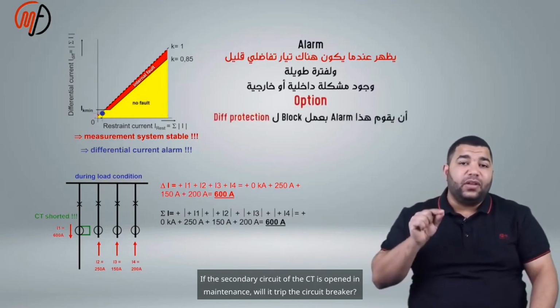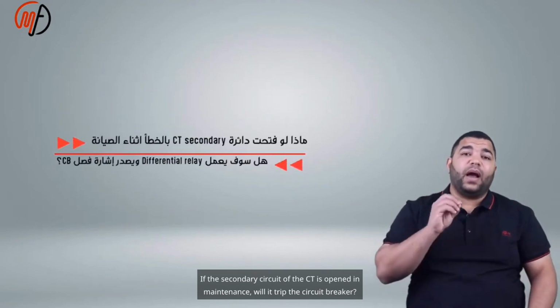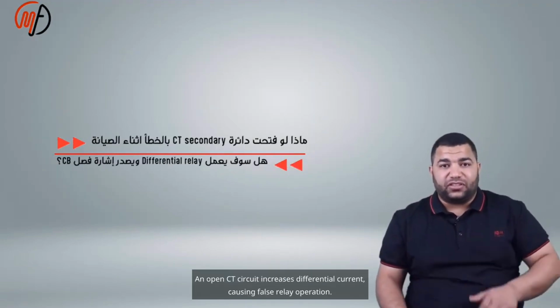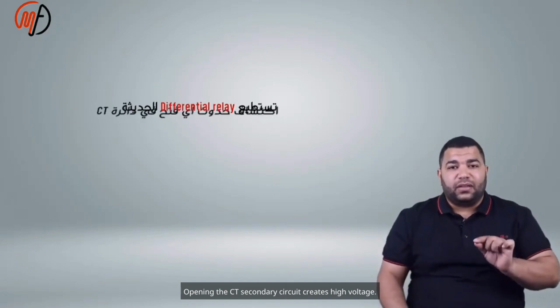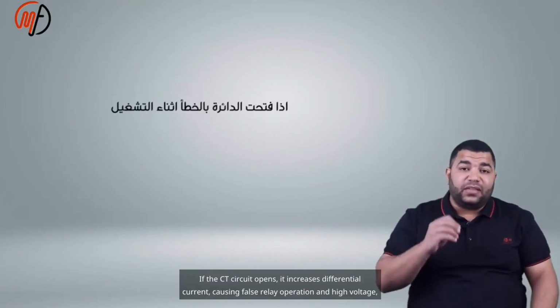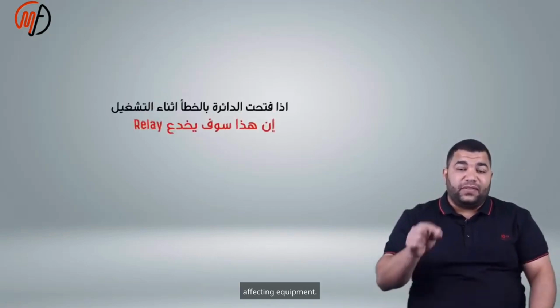If the secondary circuit of the CT is opened in maintenance, will it trip the circuit breaker? Modern relays detect CT circuit openings. An open CT circuit increases differential current, causing false relay operation. Opening the CT secondary circuit also creates high voltage, affecting equipment.